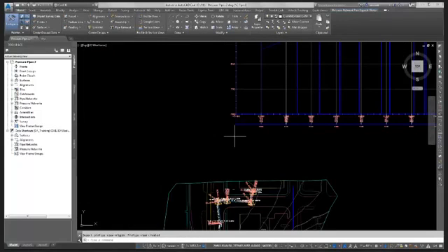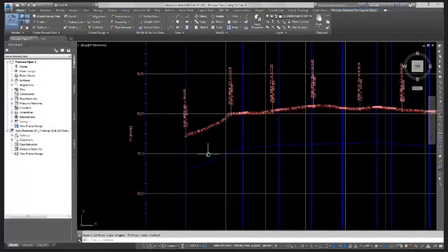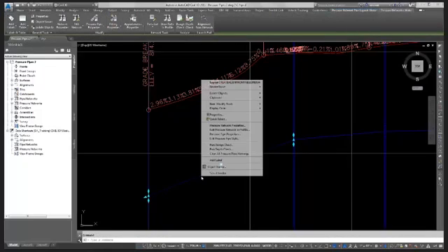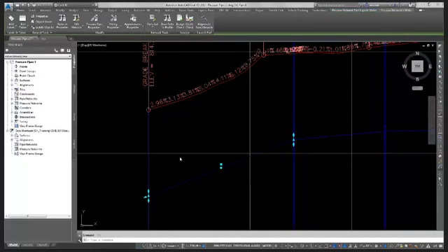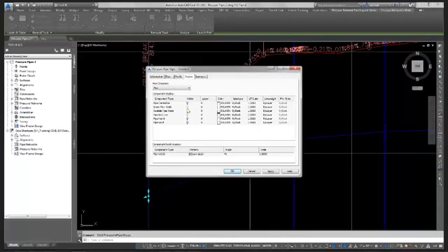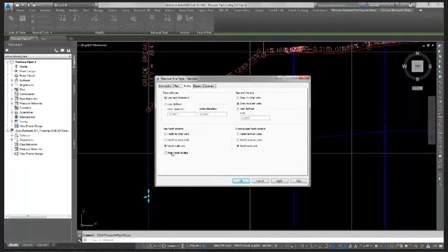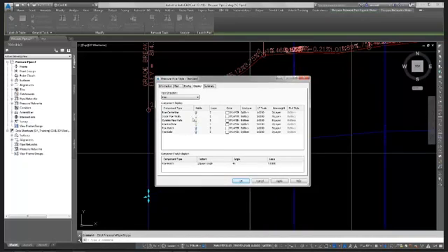And I now have what my pipe looks like in profile view. This is my first tip: I'm always showing the center line of my pipe, because if I come into my edit pressure pipe style, if I show inner pipe walls, outer pipe walls, which is funny because it's actually profile view, display, center line, apply, okay.